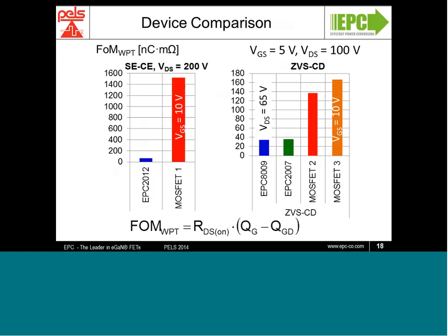But as soon as you vary the load and as soon as you change the coupling factor, you will see that the operation of the Class E will deviate from the ideal, and the voltage across that device can go as high as 6 times the supply voltage, necessitating a device in excess of 150 volt capability.